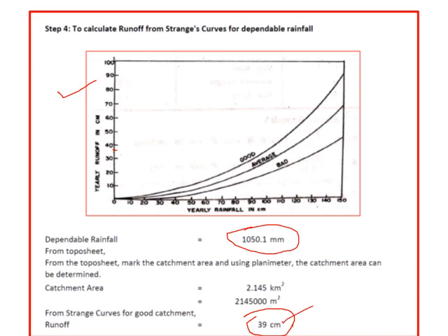So now the next step is to know the catchment area. It is not the capacity contours that you have generated, and the area enclosed between the curves is not the catchment area. The catchment area is totally different. What you have to do is take a topo sheet, mark the ridge lines, and then get the catchment area from the planimeter.